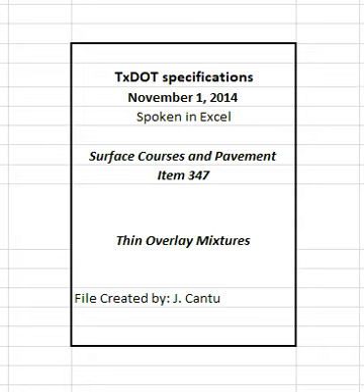The contractor may also request referee testing if the engineer's test results require suspension of production and the contractor's test results are within specification limits. Make the request within 5 working days after receiving test results from the engineer. Referee tests will be performed only on the sublot in question and only for the particular tests in question. Allow 10 working days from the time the referee laboratory receives the samples for test results to be reported.